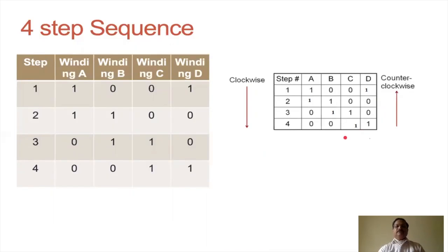So either 99 or 33, the count has to be loaded initially and then rotated 1 bit at a time. So the motor will move through a 1.8 degree step angle each time.